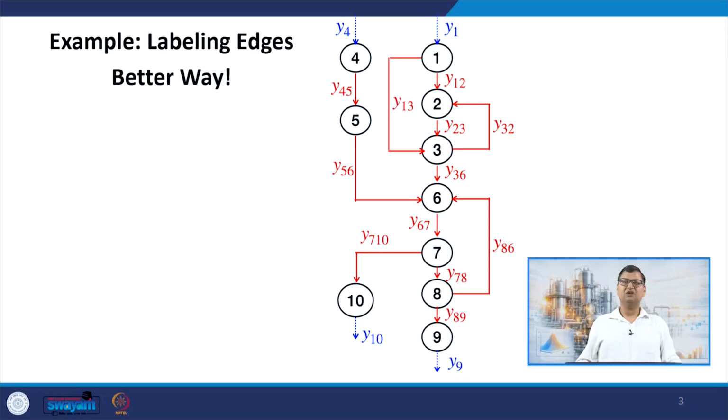So let's say this is the graph, and this graph now, for example, can be some flow sheet for which we want to do material balance equations, and these vertices may refer to different units in the flow sheet, and for every unit we may have some balances on the edges, which are the flows that are coming in and going out of the units, right. So, in order to do that, what we will first do is to renumber our edges in a more intuitive manner, and we do that in the following way.